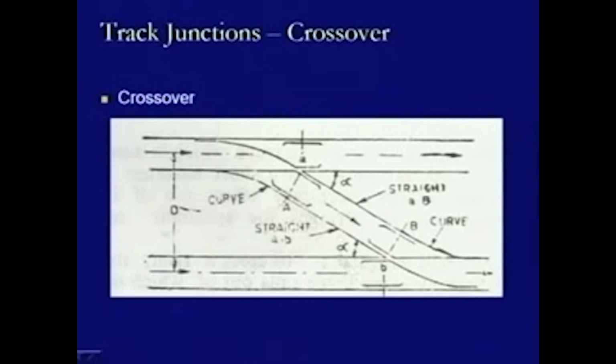And here we have a crossing at this location, and we have another crossing at the bottom also, at this location. So, we have a pair of wing rails here, a pair of wing rails here, a check rail on this side, a check rail on this side, and check rails here also. So, two pairs of check rails are there. Then there is one point and switch here and one here. So, two pairs of points and switches will also be provided in this case. These are the constituent assemblies for any crossover.